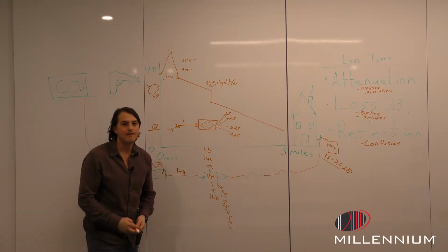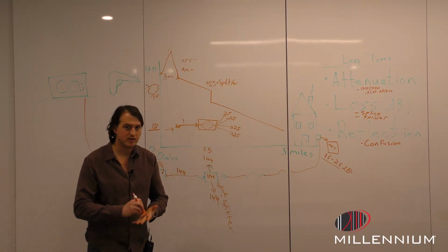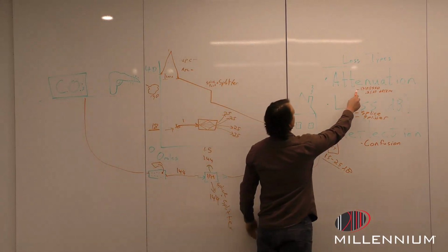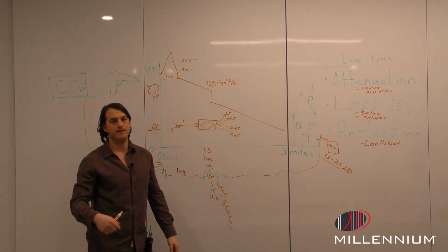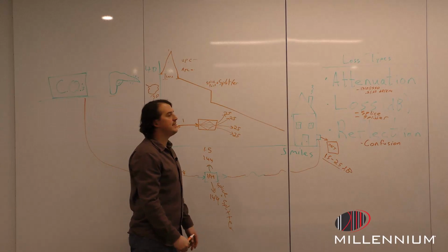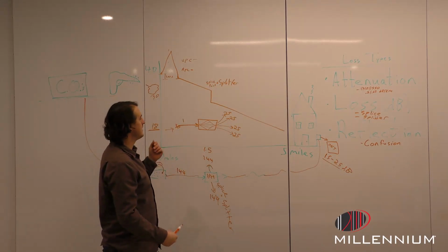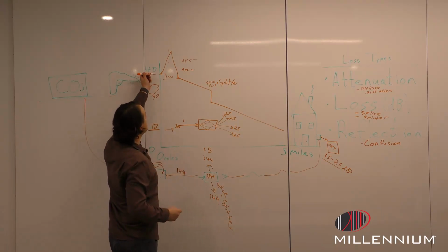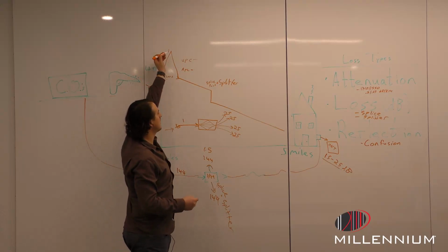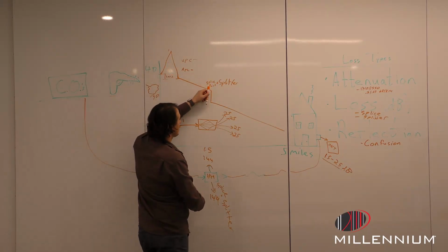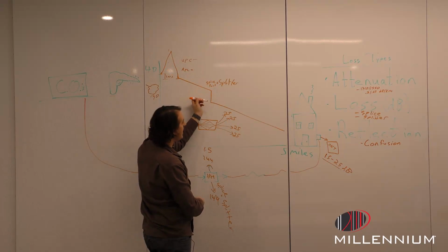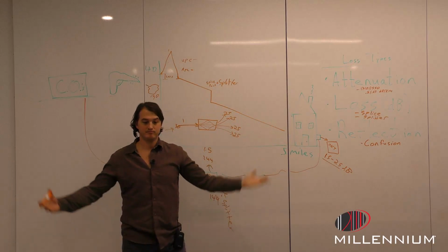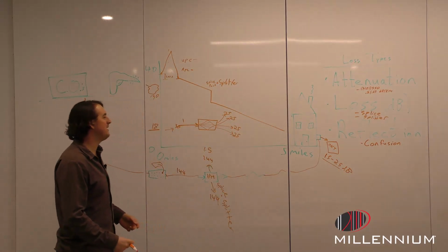And whenever we are testing with an OTDR, we are always shooting at two wavelengths, 1310, 1550. 1310 is a hyper wavelength. It's an El Camino car. It can go through turns real easy, real fast. So as we use our OTDR, we shoot our spitball. It goes through the patch panel, through that connector, goes through the splice point into the splitter. That's fine, 1310, it's flying through there. And it goes all the way to the house, and it says, hey, I'm good, man, I got here. I'm El Camino, I'm cool.